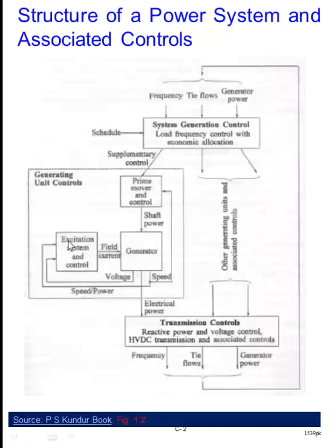Frequency, for the control of the frequency, it is through the governor, which we have here, right? But why do we have this signal which is being fed to the excitation system? If you remember from the previous discussion, we had one of the topics, that is the power system stabilizer. So if you refer to the power system stabilizer, it may use a feedback signal. It could be the speed signal, or it could be, although it is given here, power or the rotor angle.